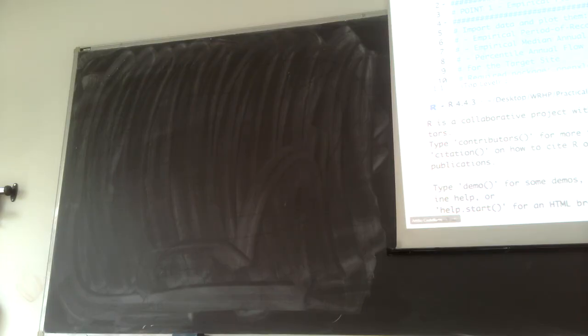If you see some red instances, please check them. If they say error, it's a big deal. It means there's something very wrong going on. If it's a warning, it can be okay. You remember this warning message? It's because I asked the program to plot some zeros on a log scale. So 0 goes to minus infinity, and it's a problem. It's signaling that there's a warning, but it's not a big deal.